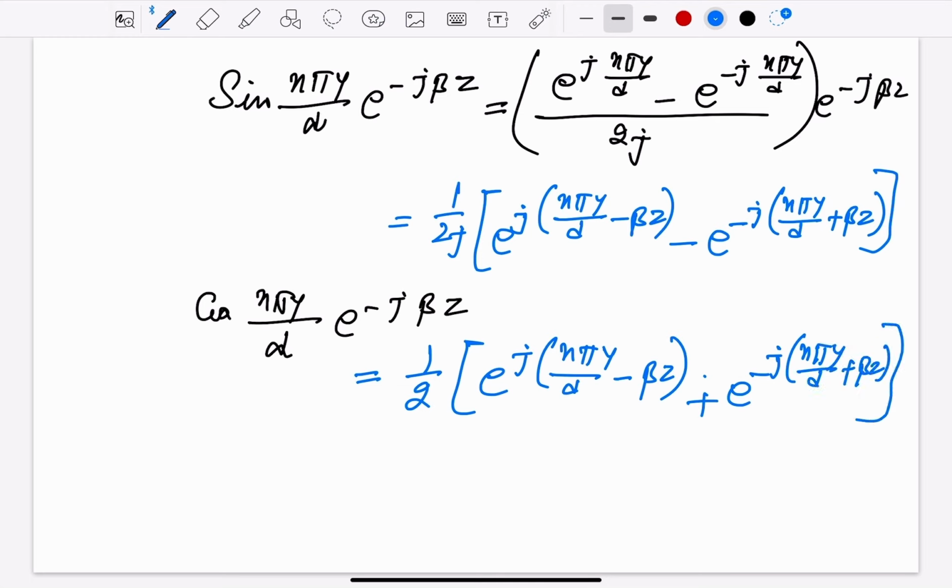Here lambda is the wavelength of the plane wave propagating in a medium defined by the material you have selected, with mu and epsilon. And for a propagating mode, when f is greater than fc, the guide wavelength is longer than the corresponding plane wavelength. I'm saying that the guide wavelength lambda g is longer than the corresponding plane wave wavelength. So this is one conclusion here.